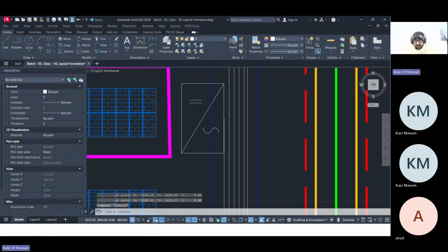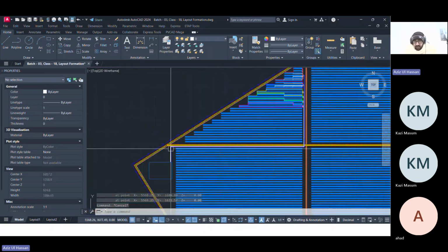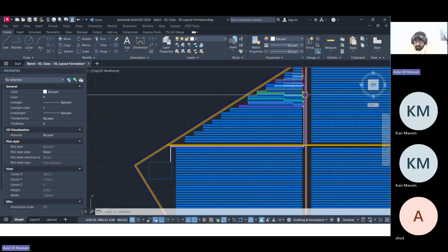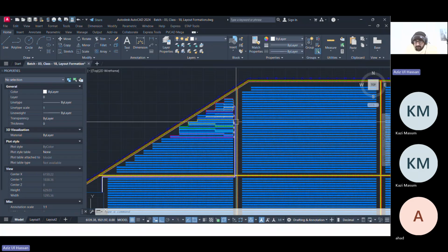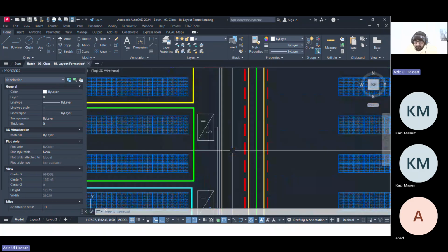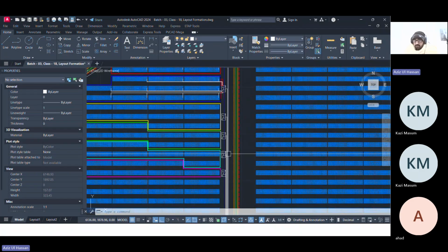So basically, these lengths are too much because we are installing the MV station here and the inverters are installed here. But in our actual practical cases, we will mark a small area where a 6.6 MVA transformer will be installed, and so the length of the inverter output cable should be as small as possible.